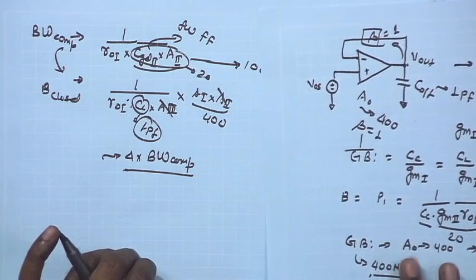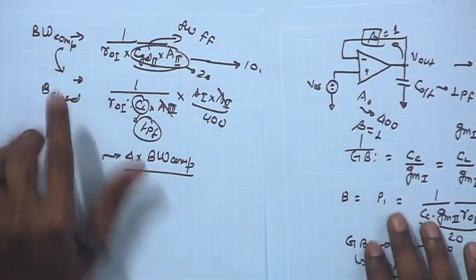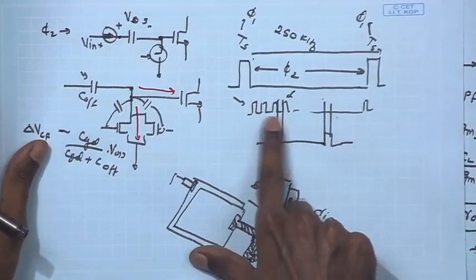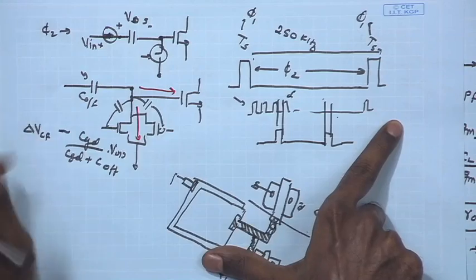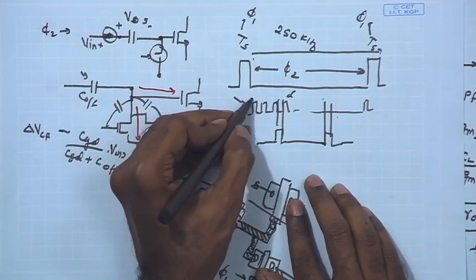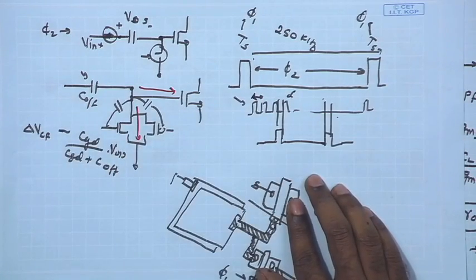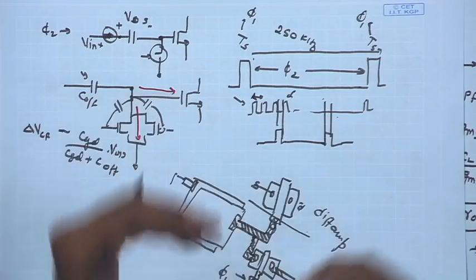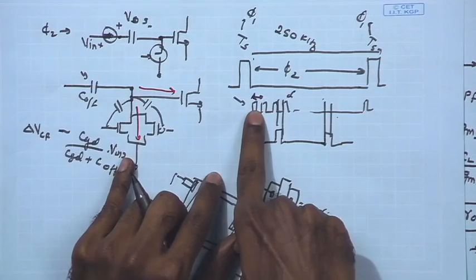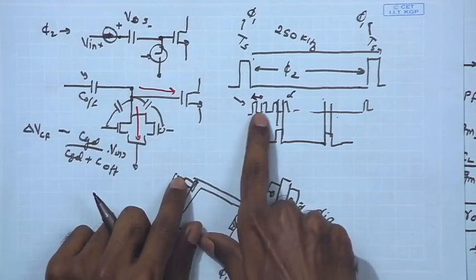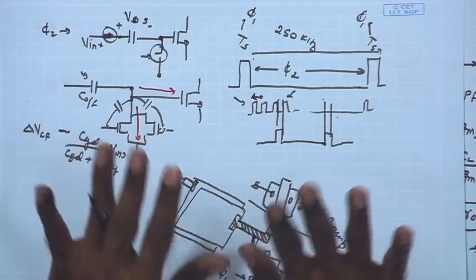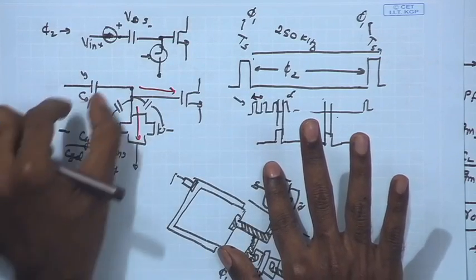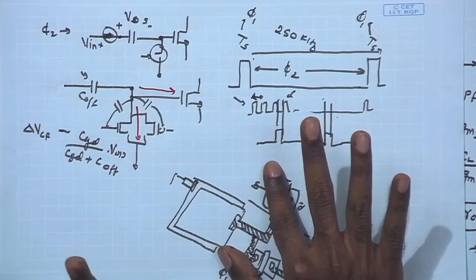So, if that happens, what will be the constraint? As of now it seems like we can go to our original waveform and our comparator can operate faster than this clock, that is how we have designed. So, within one clock period it can settle nicely. The closed loop bandwidth for the unity gain feedback is also even further larger. Therefore, within one clock duration it can do the offset calibration, it can store the offset value across the C offset. That is what we are concluding.